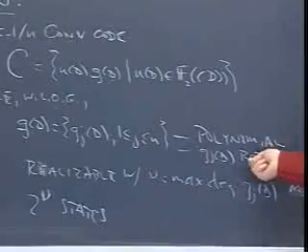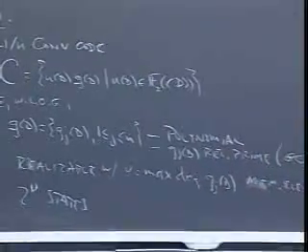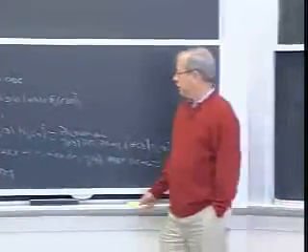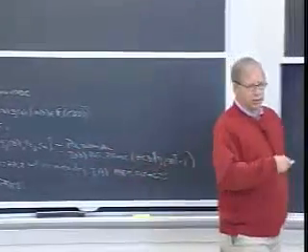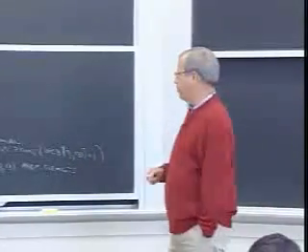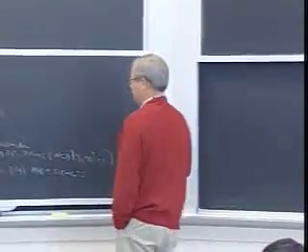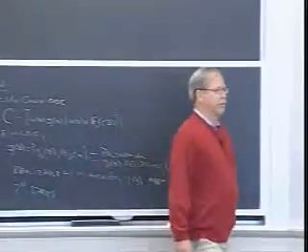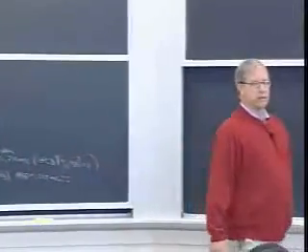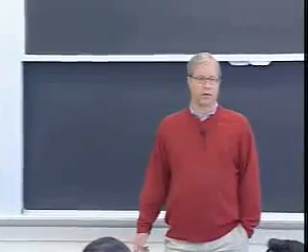So that's a nice canonical encoder to take. It furthermore has the property that there's an obvious realization of this encoder in the shift register form with nu memory units, and therefore 2 to the nu states. And we will prove in Chapter 10 that this is the minimal possible encoder for this code.